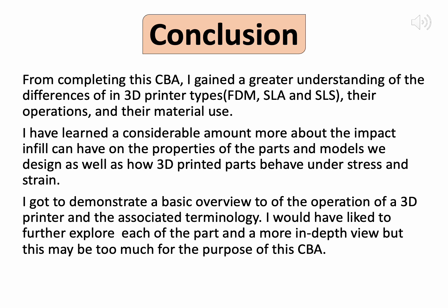I also learned more about the way we design our parts to be printed, our models to be printed on 3D printers, and in particular how our design can impact the model overall. I also learned more about how the properties and the infill have a major impact on our final designed parts, especially when we consider how much infill to include, and we have to be cognizant of this when we design parts, as well as the weight and the impact that can have on our parts.